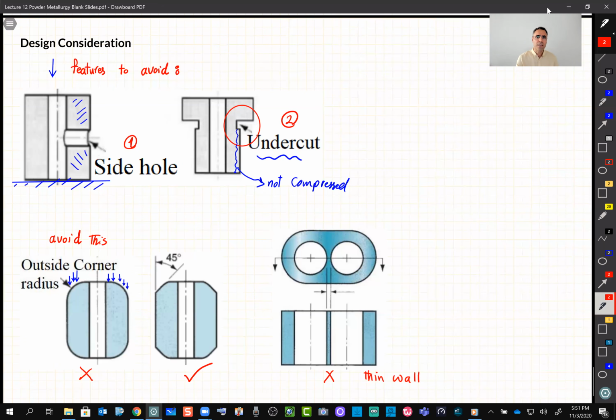You have the powder, you need to be careful with powder because it is explosive, and also handling it is difficult. People working around powder have to be careful about inhalation because some metal powders are poisonous, or even for non-poisonous metals, they are still bad for people.